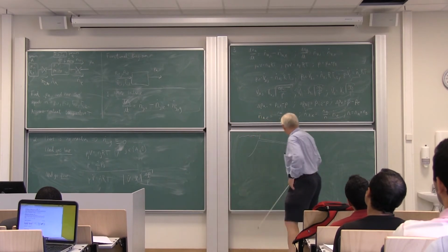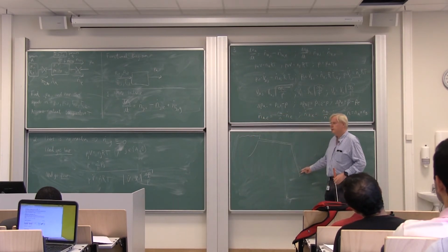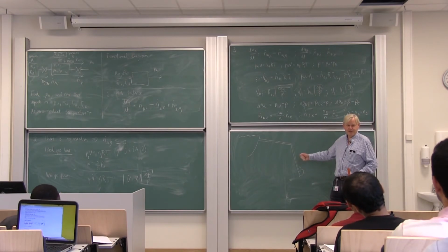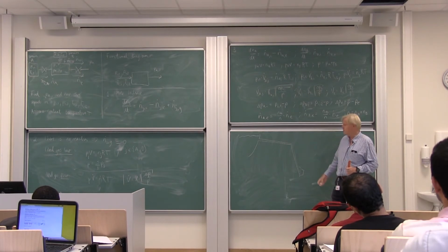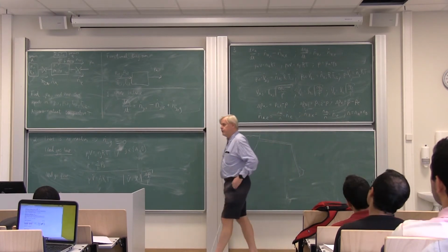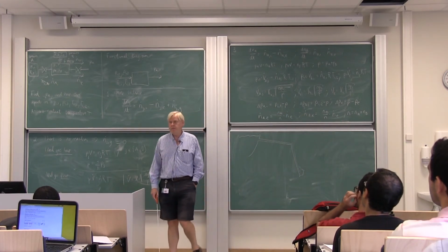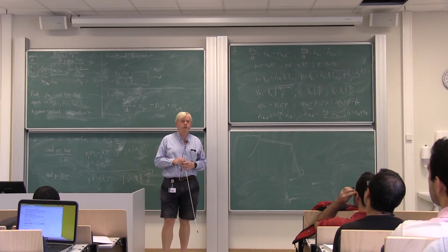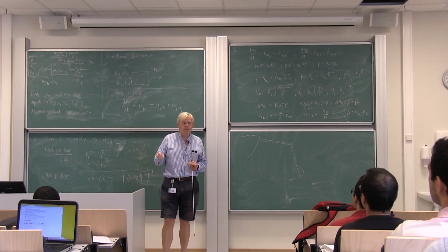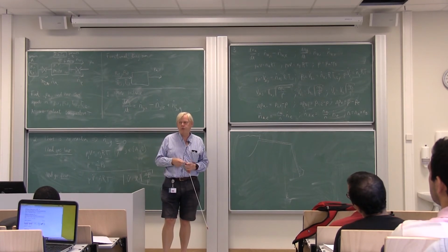So in this case, if you do some variation in the turbine opening, you can easily understand that you can actually get compression of water and very high pressures. So that's one example where even for liquids, when you describe the model, you may need to take into account that the flow direction may change, and then everything becomes more complicated.